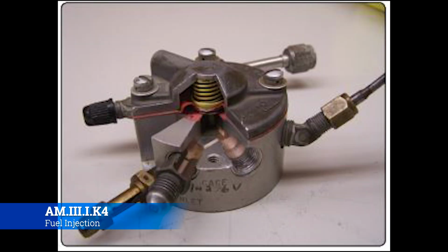Okay, so this is what one looks like in real life. These will typically be mounted on top of the engine, and you'll have little stainless steel lines that will go off to the individual injectors at every cylinder. There's also typically a return line that will go there, as well as a supply line. So if you have like a 6-cylinder engine, you're likely going to have at least, say, 8 of these little guys that will spider out and go to different places.